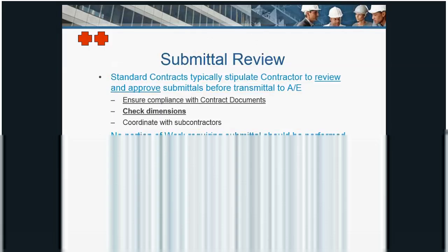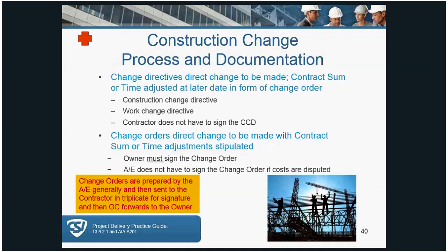...in time, and sometimes the value of that change is going to occur at a later date. You may not know what the cost of the actual work may be until you actually get completed with the work, and so that's when a construction change directive might be used. If you uncover and damage a plumbing line that wasn't shown on the record documents or the survey, then a construction change directive might need to be issued to keep the utility in place and get it repaired.